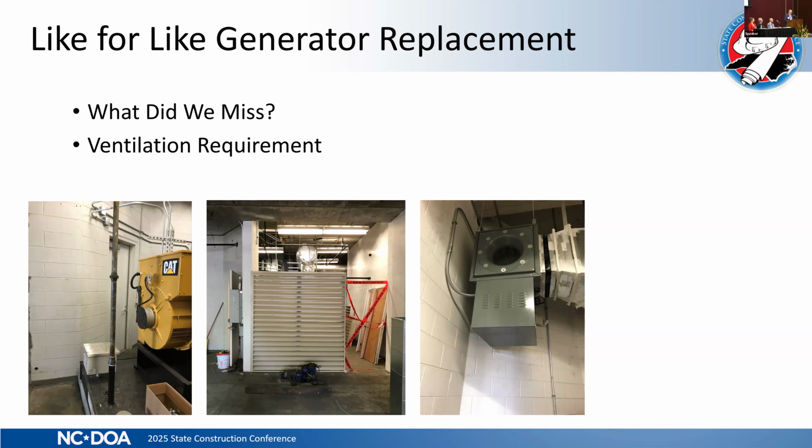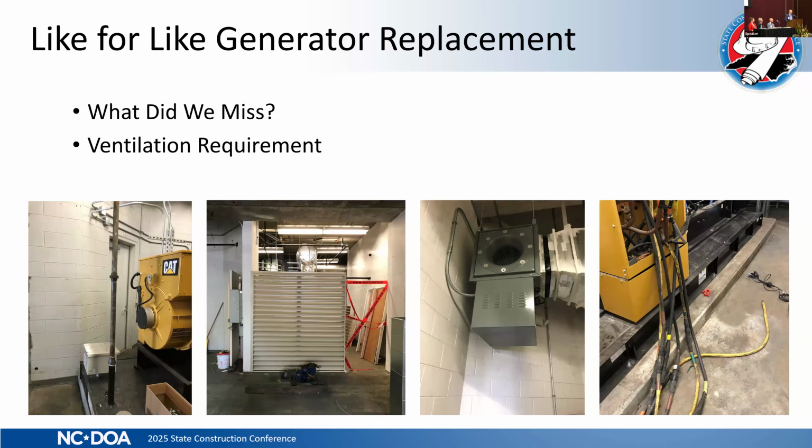Okay. Months later, the generator arrived. The generator sat out on the street as the riggers came in to remove the existing generator. That is when they decided to measure the pad, the concrete. Yes, so same size generator. Oh, as far as capacity. Physically, the new generator was larger and would not fit on the existing pad. The contractor had to pour a larger pad, wait for it to strengthen, and then place the generator in there. Okay, pad, find number 2.